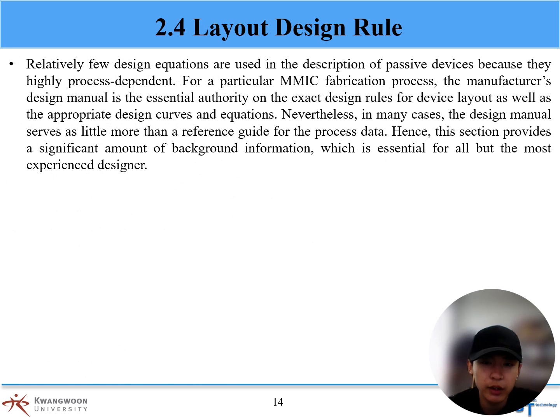Next is the layout design rule. Relatively few design equations are used in the description of passive devices because they are highly process dependent. For a particular MMIC fabrication process, the manufacturer's design manual is the essential authority on the exact design rules for device layout, as well as the appropriate design curves and equations.